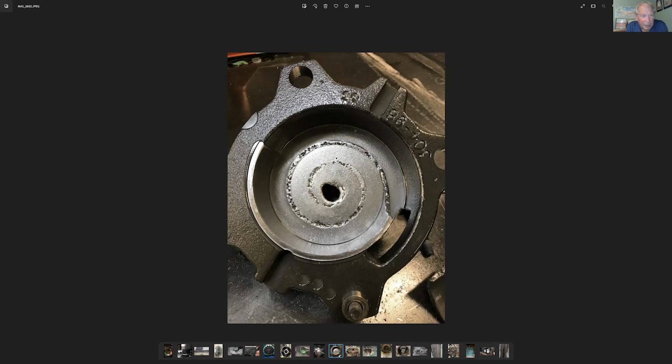Has anybody dealt with a system that had a solenoid valve for pump down prior to shut off, where your low pressure switch controlled your compressor contactor rather than a thermostat? What happens if that solenoid valve is bleeding through during the off cycle? And that's something you're not going to see. Typically, you're not there to watch compressors that aren't running, but there's lots of things that can lead up to that, that you can plan for to minimize that migration during the off cycle. But if the solenoid valve bleeds through, or there's just too much going on, the evaporator's flooded more than it should be.